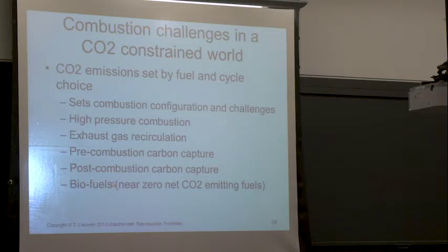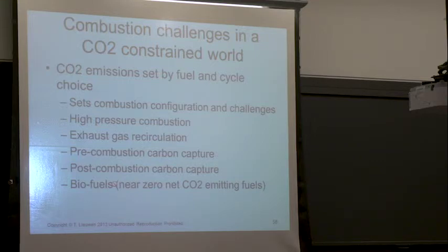It's been done, and for example, South Africa does this to generate jet fuel. If you've ever flown from South Africa, you have flown in a synthetic hydrocarbon. It's a synthetic jet fuel generated in that case from coal, highly non-CO2, but it's the same basic process. You take coal, you gasify it, you form CO and hydrogen, you run that through a catalyst, and then that forms a synthetic fuel.